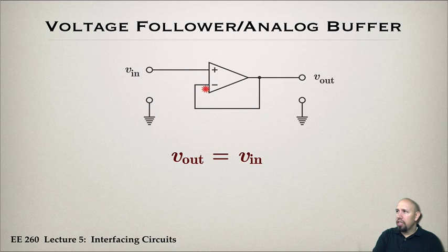Notice that in this case, it's coming into an op-amp which has high input impedance and low output impedance. So by connecting this circuit up to another circuit, the combined circuit now has low output impedance. And since I have very high input impedance here, this circuit does not load my other circuit.